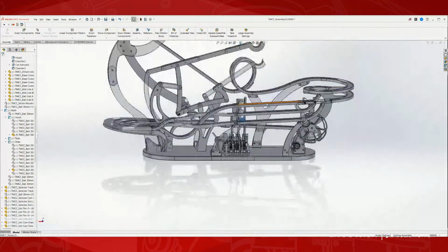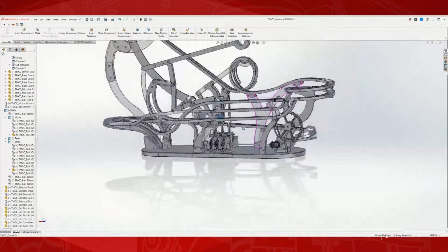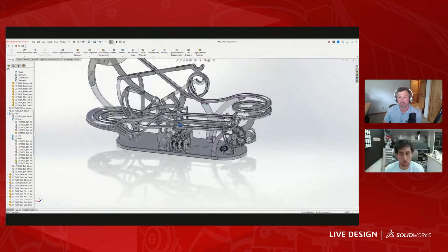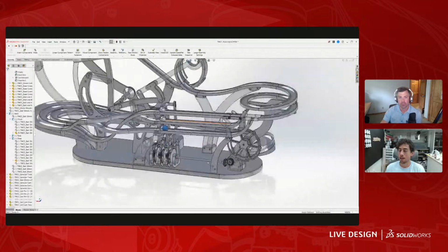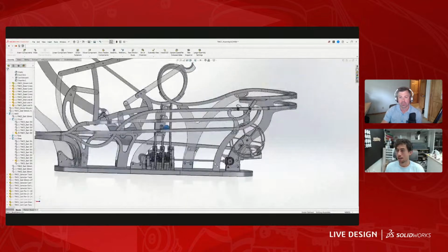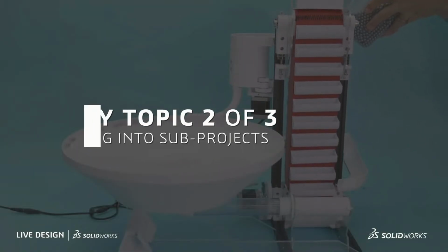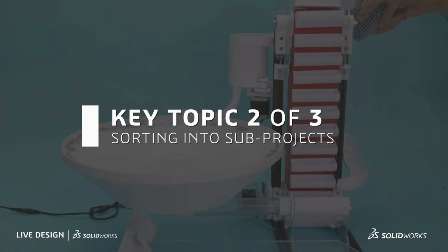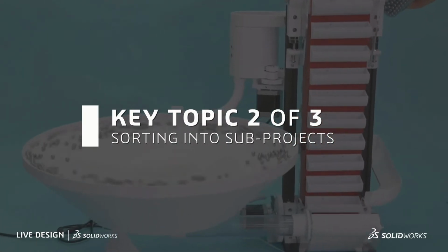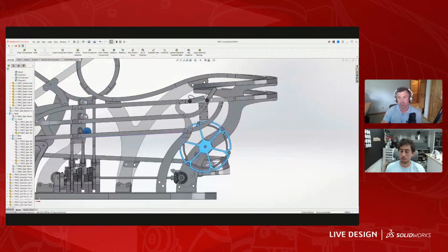So this was complicated when I'm talking about it like this, but when I broke it down into its sub pieces and just worked on one of these things at a time, it was like, for this cam right here, I knew I needed to open a gate and close a gate every 10 minutes and then open or close both gates every hour to drop a ball into the hours track. And that was as simple as just one cam per each of these tracks. And you can see they rotate and then rotate. And then when they get to this point here, they both drop down.